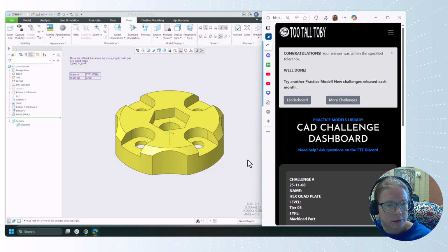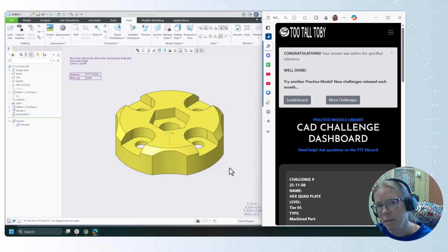And what did we do that was interesting there? We used sketch region to make a quarter piece of it and then pattern it. We made a datum axis on the fly. So while we were in there and realized we didn't have one where we needed it, we could add it while we were making it. The shell in Creo is always a nice tool where we can set non-default wall thicknesses.